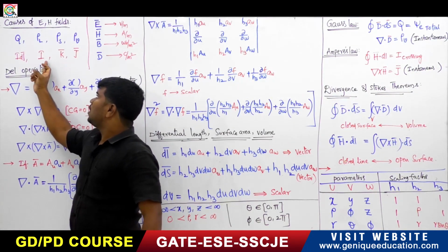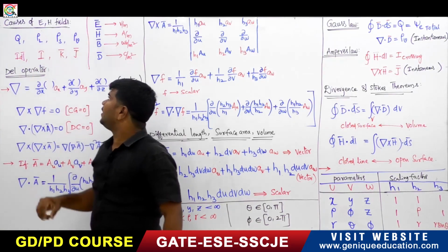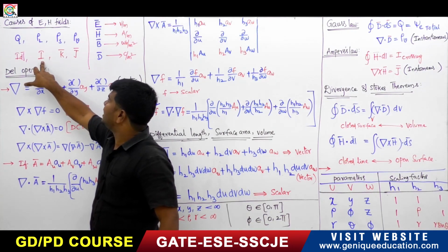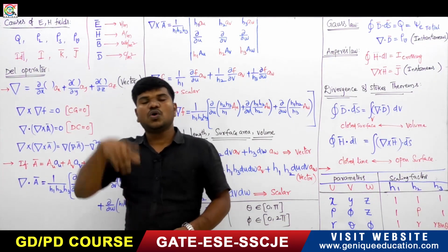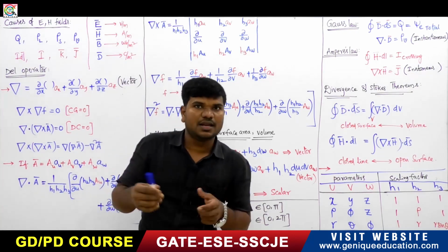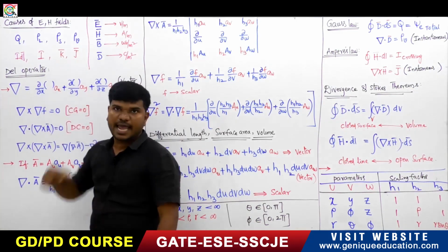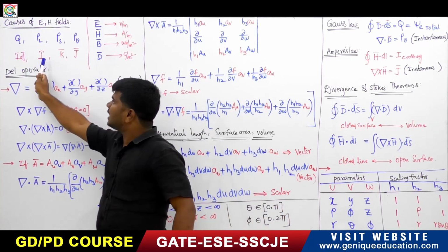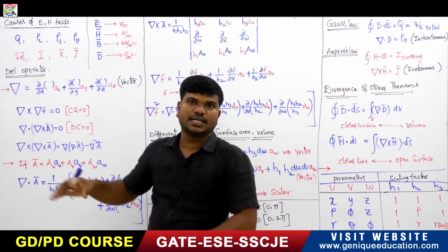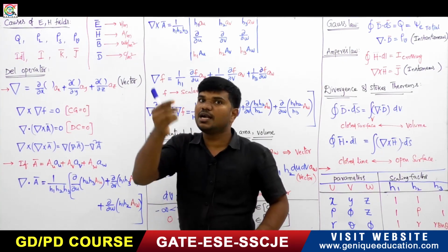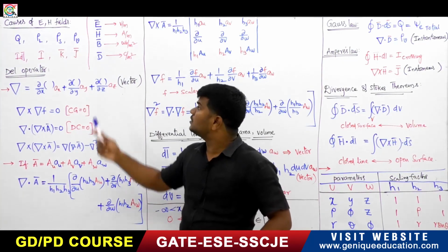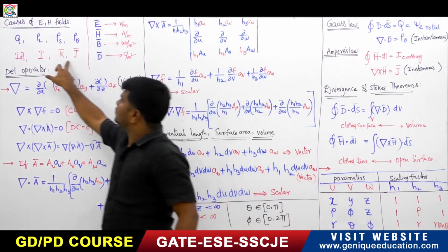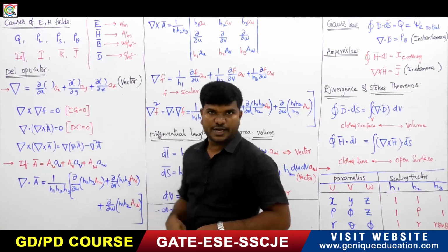And we know a current carrying wire is generating the magnetic field. Also, if the same amount of current is passing through a sheet of length L, then we name this one K, and it is called the sheet current. Suppose the same amount of current I is passing through a solid conductor, we name it current per cross sectional area, so we call this one J. All these four will give you the magnetic field.